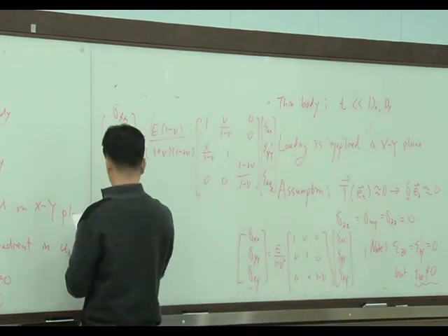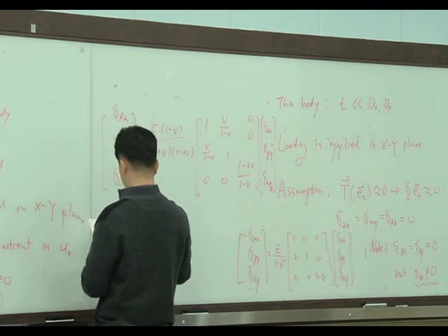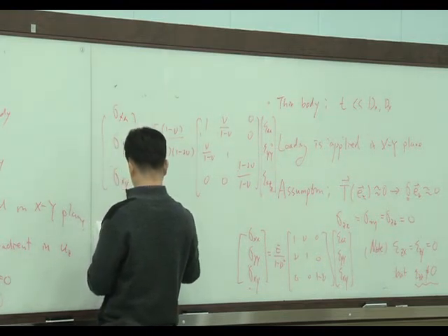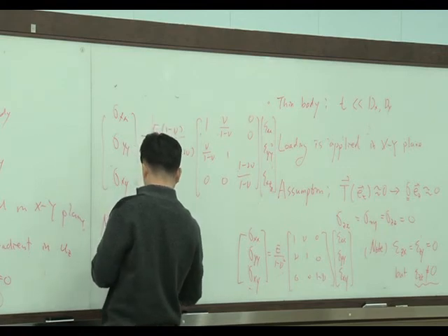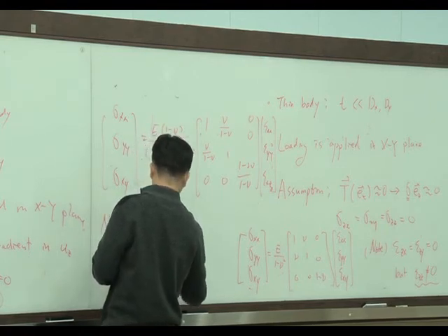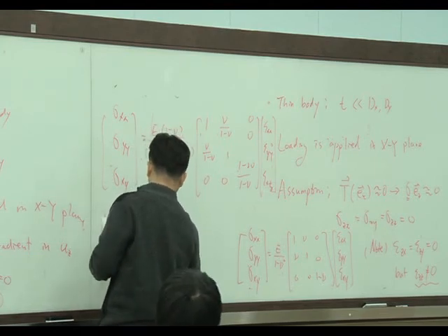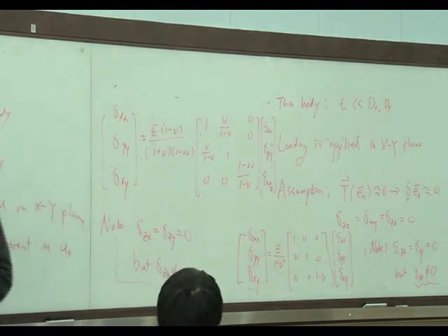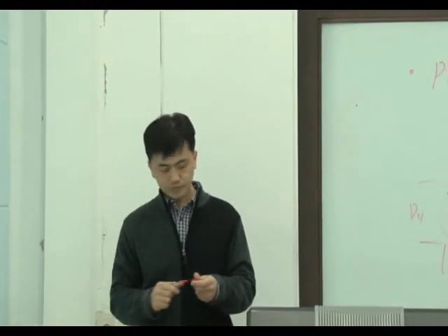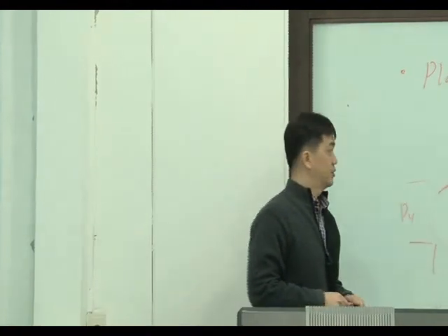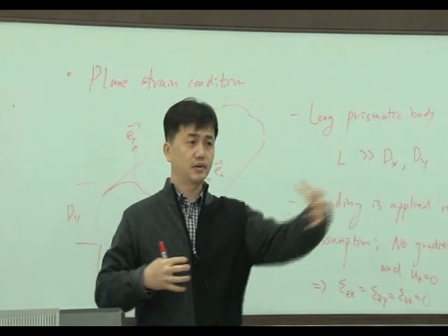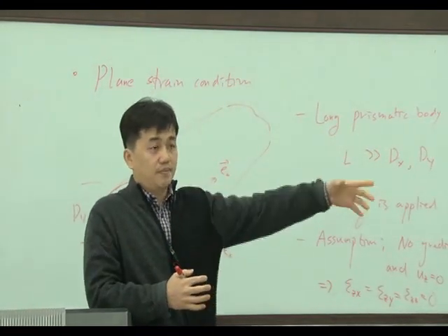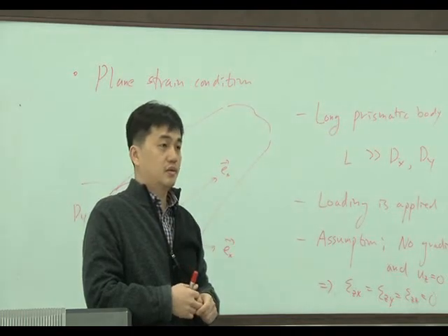Similarly, I need to note that strain zx and zy equal 0, but stress zz is not 0, actually, due to the Poisson effect. We can use the plane strain condition for the analysis of very long structures like a dam and breakwater.